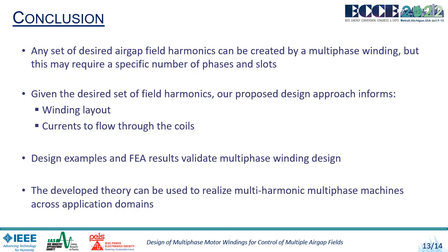So in conclusion, this paper presented a design technique to realize multi-harmonic multiphase windings, that is, multiphase windings that can create multiple air gap spatial harmonics. The results in this paper show that any set of desired air gap field harmonics can be created by a multiphase winding, but based on the number of air gap field harmonics to be created, this may require a higher number of phases and slots.